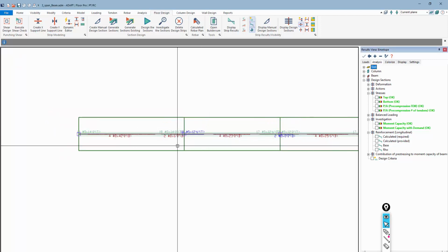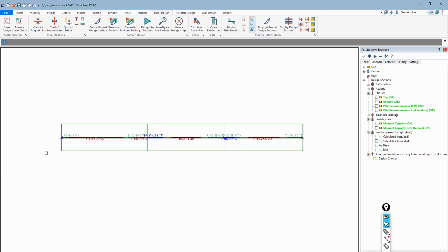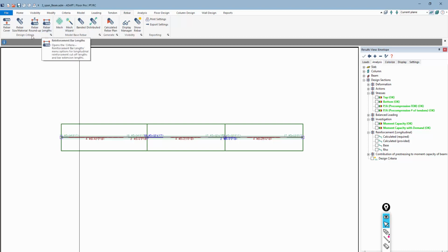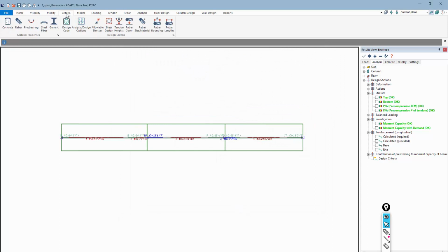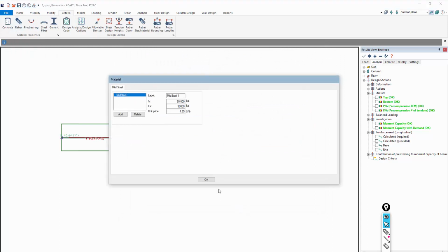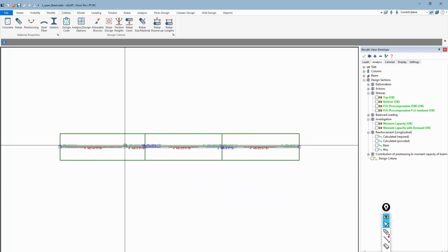Okay, so there's additional reinforcement reporting graphically here. If you want to change the bar sizes that the program is using, we can go to reinforcement and define the size of material here for beams. Top and bottom, stirrup sizes. Material assignments are shown here, but that's actually defined under criteria for rebar material. Okay, so there's a lot of opportunity here for the user to just model simple beams, continuous beams, and use Builder in this format to generate designs and evaluate beam frame type systems.